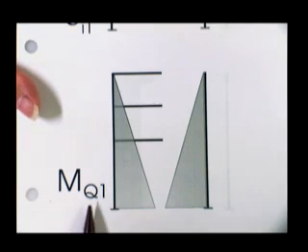There's your M sub Q due to a unit load in the number one direction. That's a good reason to call it the number one direction, the number one load, the number one anything. Because if you start saying it's M sub Q at A in the horizontal direction due to something in the vertical, you just get lost.